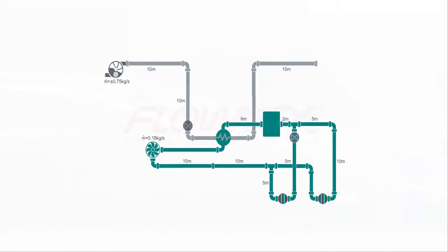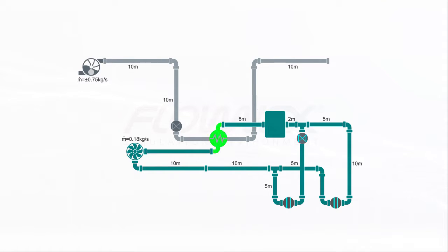Let's quickly look at the system again. We have hydrogen that is cooling our generator, and we need to achieve equal flows through the generator cooling lines with 50 kilowatts of heat load and 10 kPa pressure loss at a total system flow of 0.18 kilograms per second. The water side will in turn take up the heat from our hydrogen and release it into our beautiful pond with all sorts of tropical fish in it, or something like that.